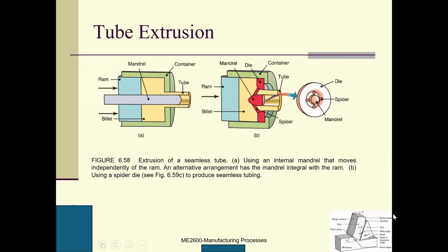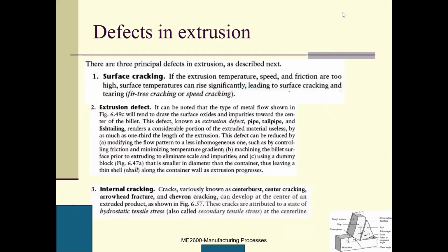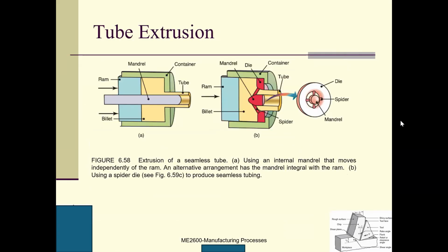No question? Okay, well. So this is kind of the same question. With the spider die, it doesn't break it up into 4 pieces. It would come back into 1 because it goes through each of the 4 quadrants. Wouldn't that break up the workpiece into 4 pieces? So this will come out. This is material coming out from these 4 orifices, right?